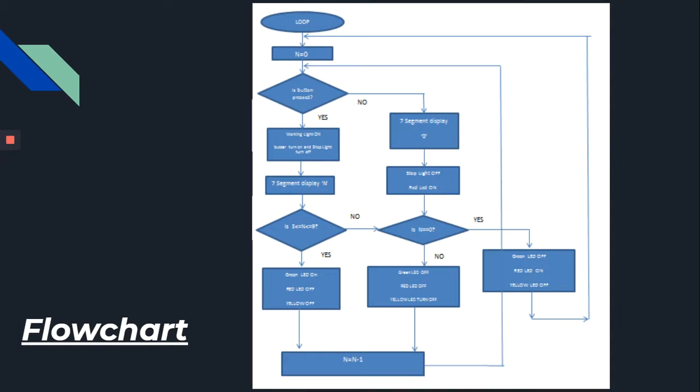And for the flow chart, this is how our looping looks. First of all, we will check the state of the number. Normally we will start with 0, and afterwards we will check whether the button is pressed. If yes, then the working light will be on and the buzzer turned on, and the stop light will be turned off.